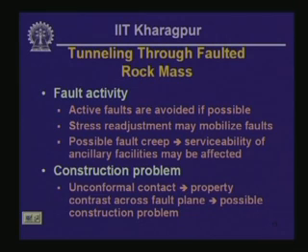and "if possible" is the key phrase there, because oftentimes you have to construct a tunnel through faults which have been active over a relatively recent geologic past, say over a few hundred years or a few thousand years. In that case, you have to account for the possible movement of the fault in the design of the tunnel itself.